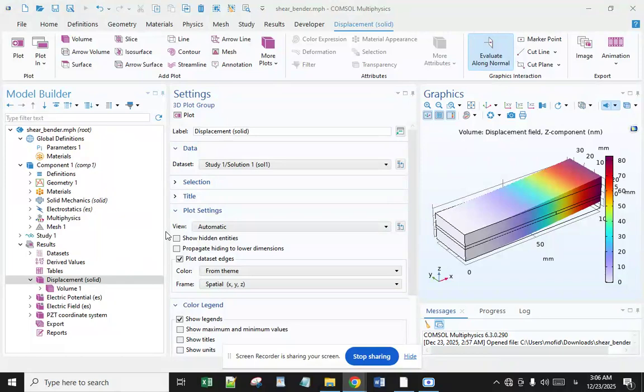All layers are assumed perfectly bonded and in XZ plane deformation state. Bernoulli Euler theory is retained for the sandwich beam surface layers, while the core is assumed to behave as a Timoshenko beam. A local frame is attached to each layer at its left and center, whereas the global one is located at the left and center of the whole beam, so that the beam centroidal and elastic axis coincide with the x-axis.